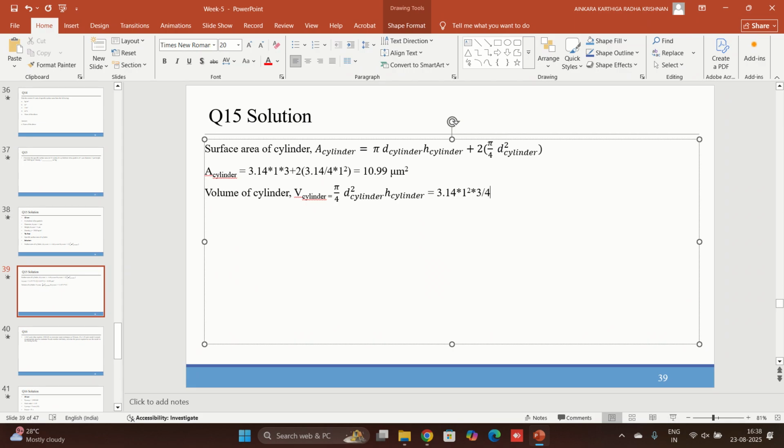We did the sphericity calculation for this particular particle actually. That is why we are looking familiar. 2.355 and it is micrometer cube. Now what we need to do, we need to know the mass of the cylinder. So volume into density will give us the mass of the cylinder.